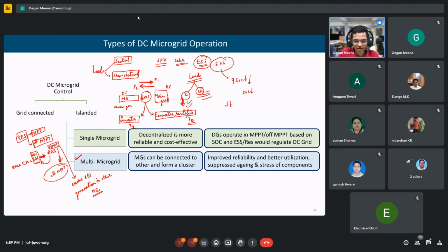Now another component in this microgrid is storage. We can have hybrid storage, as we have seen in week 3 also. One is battery, the second one is ultra capacitor. Which one has high power density but low energy density? Which among these two? Ultra capacitor has high power density but low energy capacity. So it is used for meeting high frequency switching transients. Frequent switching operations and spikes can be met by this ultra capacitor.